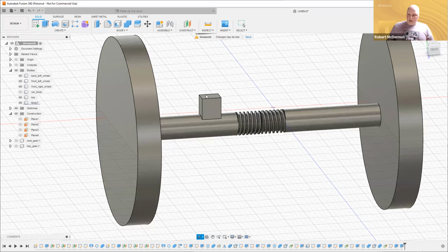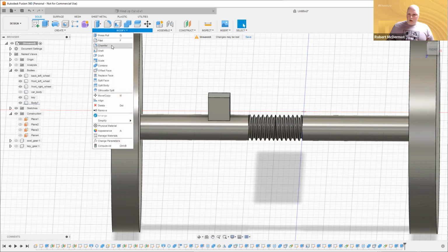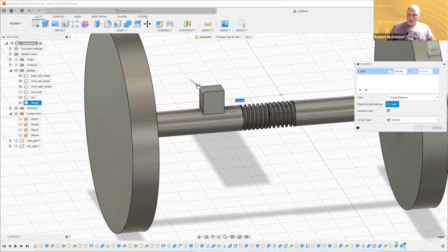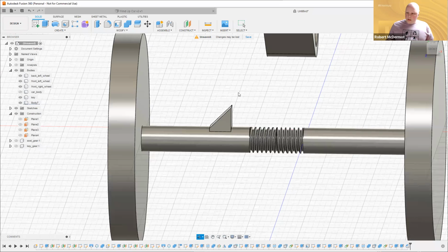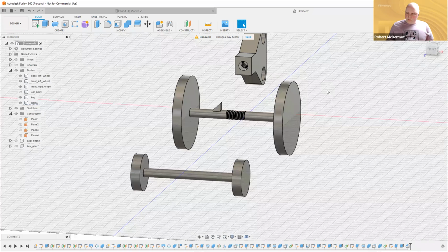Well, we don't really need this whole bit. Instead, if you know about 3D printing, one of the safe things to think about, as long as something is 45 degrees from the ground plane, like this will be enough. The print will be able, there'll be enough overlap, and it can print this shape without it falling. So I'm going to put a little chamfer there, make that 45-degree angle. And now this bit can catch a rubber band and it will be printable.